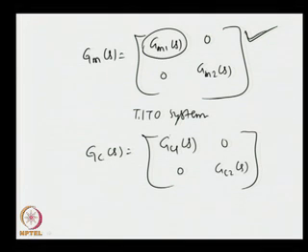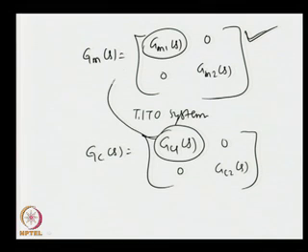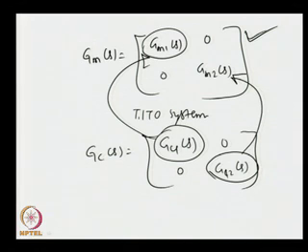Now, the controller GC1S will be designed based on the dynamics of GM1S only. Similarly, the controller parameters of GC2S will be obtained purely based on the parameters of GM2S, thus giving us freedom to design the two series PID controllers in a way we have designed for SISO processes.